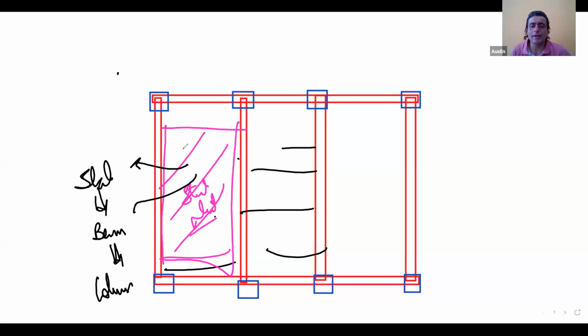But using a steel plate is problematic. Why is it problematic? Because steel plate thickness is very small. So because of small steel plate thickness, it will not be able to act as a proper formwork for larger spans, isn't it? You understand? If I'm using just a thin steel plate, I'm showing you the cross-sectional view. And now this is my RCC slab.